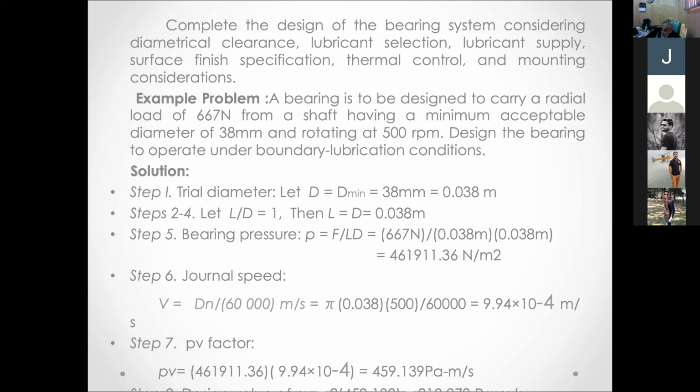Thermal expansion of the bearing which takes place. These things are to be considered, and also for maintenance, clearance is to be considered. So your clearance is based on 2 or 3 factors. That much clearance you should provide always in the bearing. Otherwise, bearing will fail. So that's another consideration in the design.